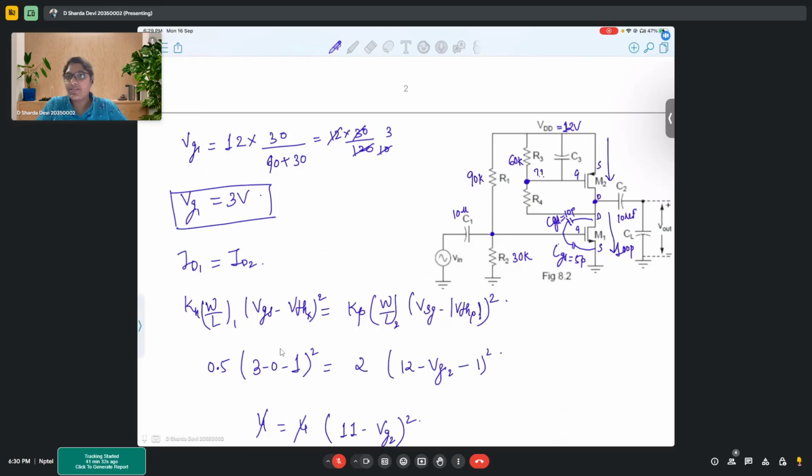If we have to even assume, we consider the saturation condition and limiting saturation condition. From there, we start and we get VDS. But unfortunately, here we didn't even know the gate voltage, and without knowing the gate voltage, finding VDS is very tricky.